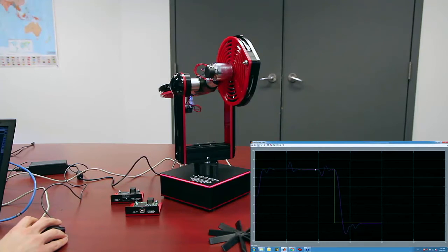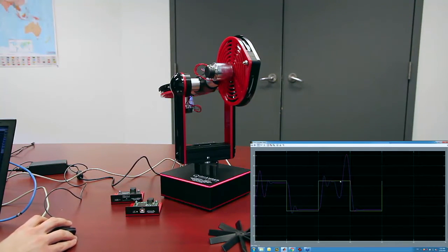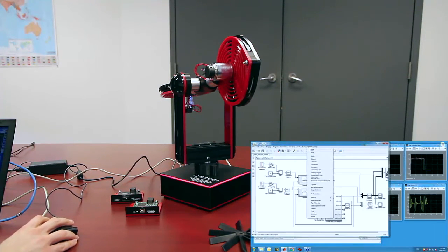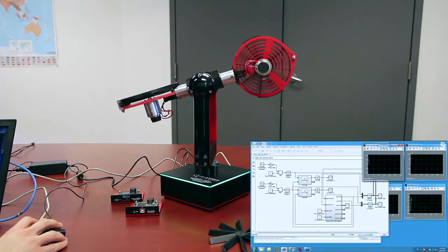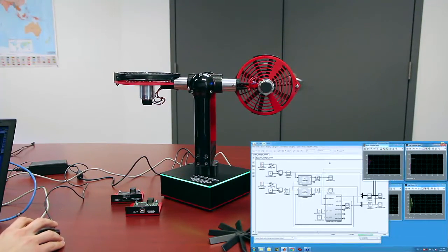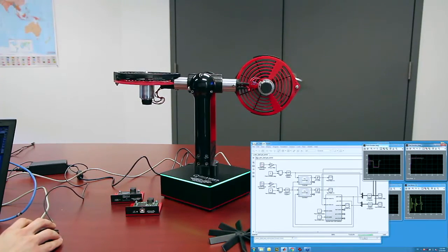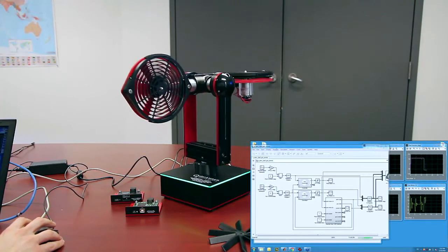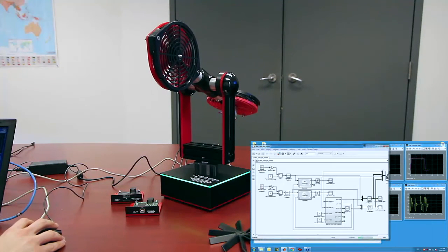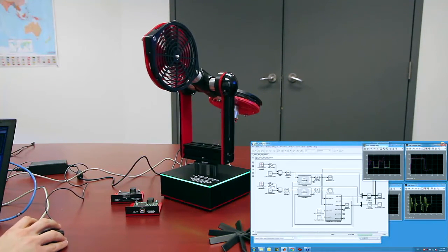When the pitch moves, you get these little perturbations, if you will, along the yaw, right? So the controller has to compensate for this. These are the torques that are introduced from the pitch when you control the yaw, and these are the same that are affecting the pitch when you're moving the yaw. Let me run it again, now that you've seen this. You can see a bit of the oscillations, a bit of the overshoots, especially in the pitch.